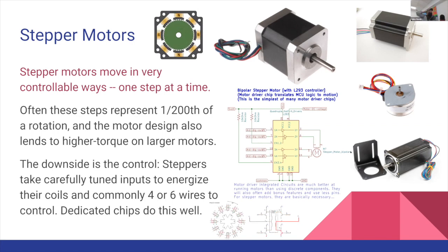And it means that this was not a thing that would have existed prior to a digital controller for a motor. We really couldn't run these. There's no way that Michael Faraday could have invented one of these. Not because it's electrically that complicated of a motor, it's fairly simple, but because you needed the electronics to control it at very high speed, so that you could get it to move through those steps.